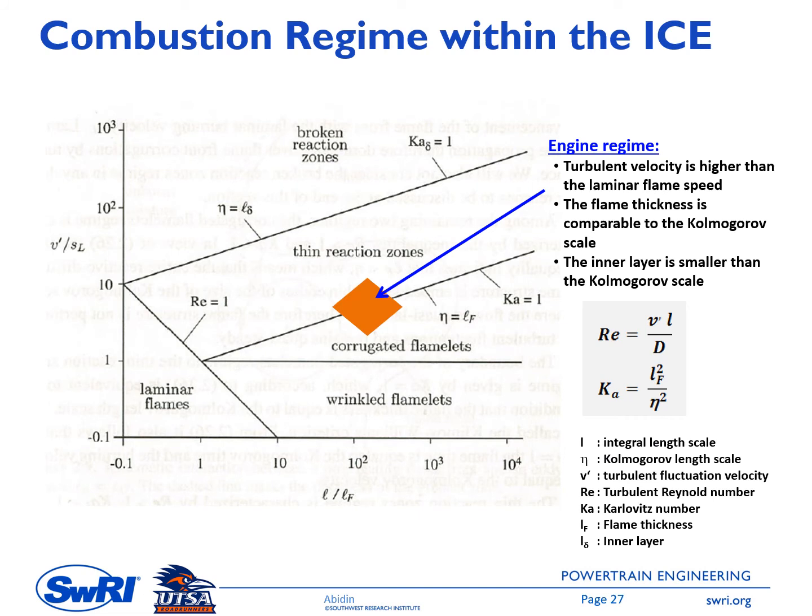This figure is just to give you an idea about the combustion regime location for the internal combustion engine when it is plotted. On the vertical side here is the turbulent level normalized by the laminar flame speed, and on the horizontal axis here is the turbulent length scale. I know this is too advanced to be introduced in this class, but for sure you will use this diagram. It's sometimes called the Borghi diagram when you learn combustion at an advanced level.